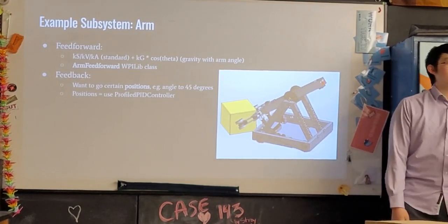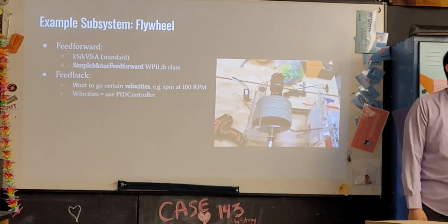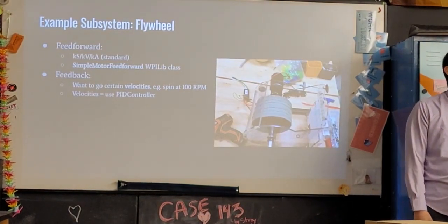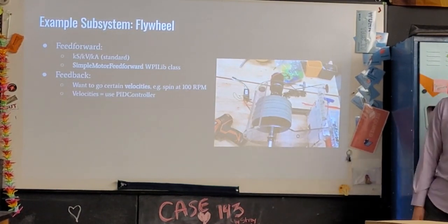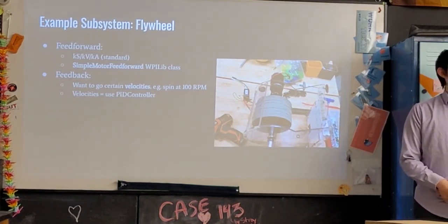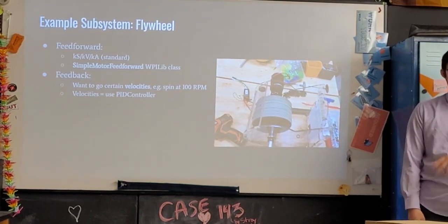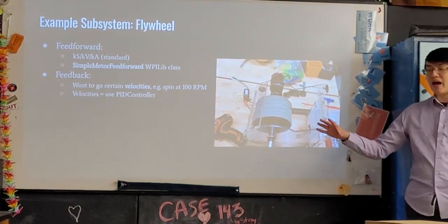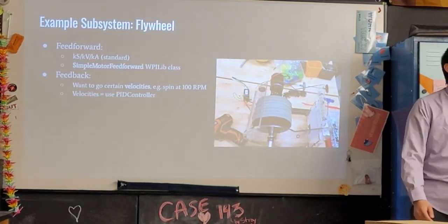We put a mechanical stop in as well. Yes. Did it go like almost all the way up? Yeah, so the profiled guy constrains acceleration and velocity, and it's up to you to constrain position. All of them have to be constrained to you. But in some of these systems, you don't know what's going to happen, so you have to be careful. Exactly. Yes, mechanical. See, once feedback corrects for feed forward, but what corrects for feedback is mechanical.